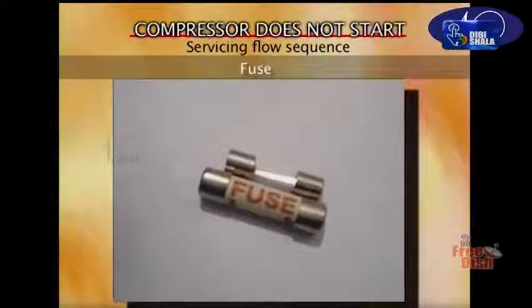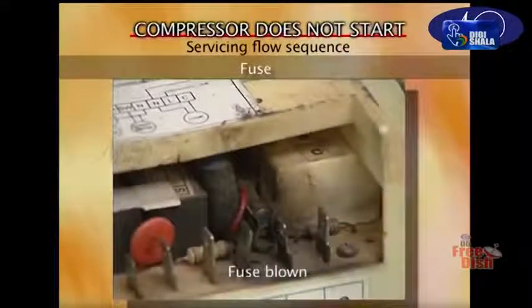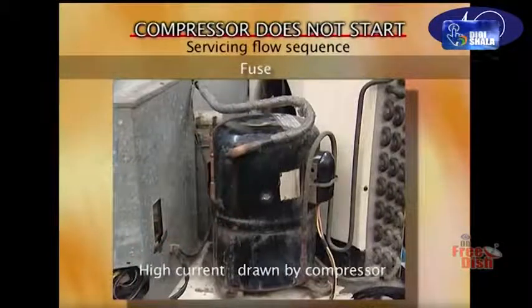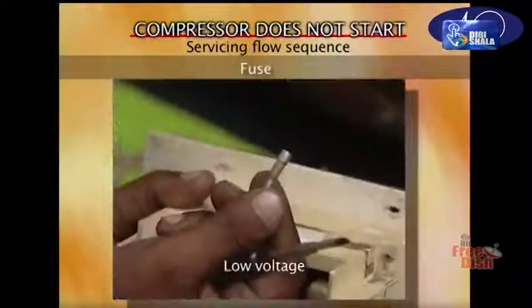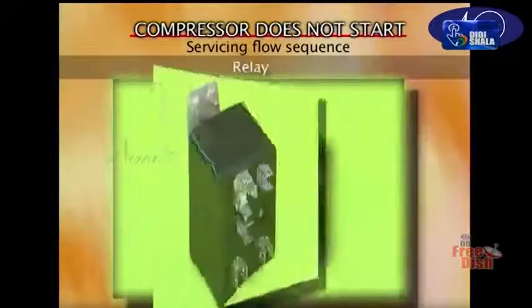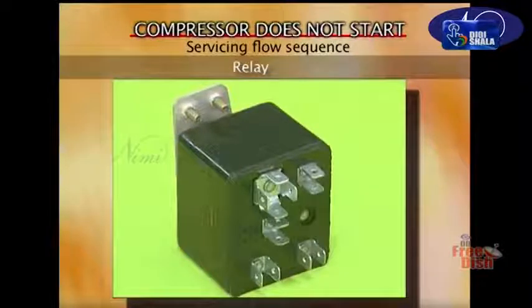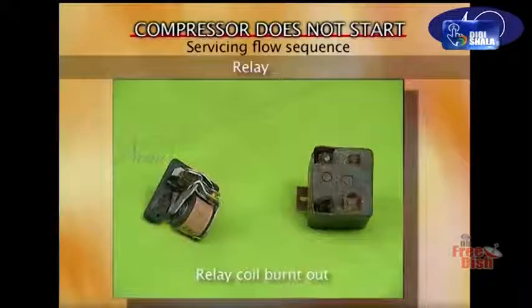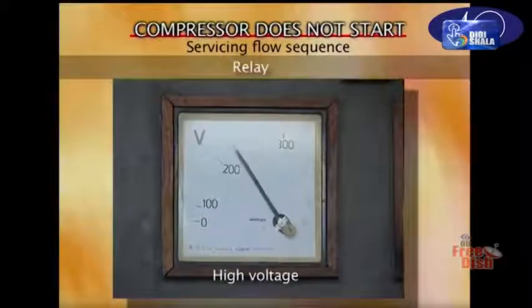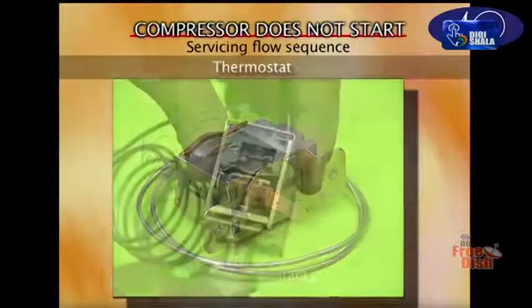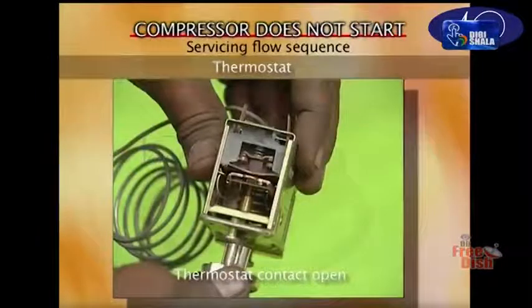Check fuse. It could be fuse blown, high current drawn by compressor, low voltage. Check relay coil. It could be a relay coil burnt out or a high voltage. Check thermostat. The thermostat contact could be open.